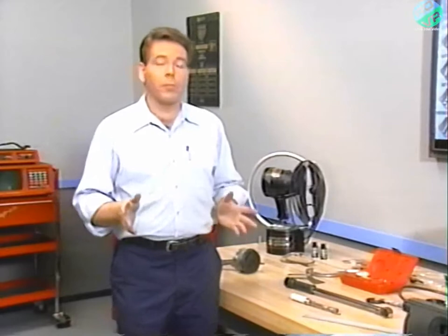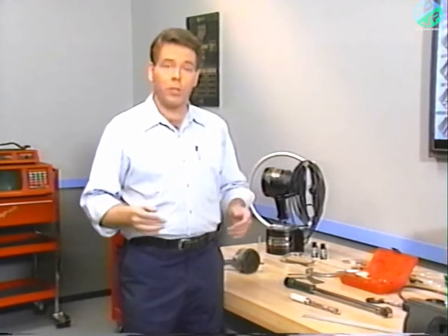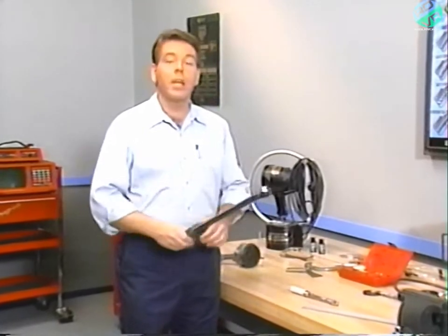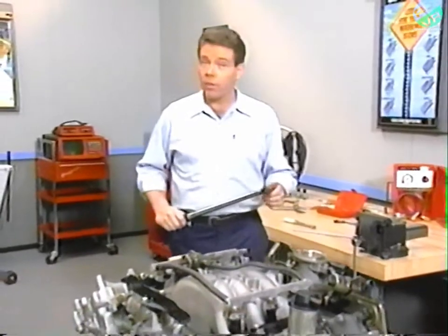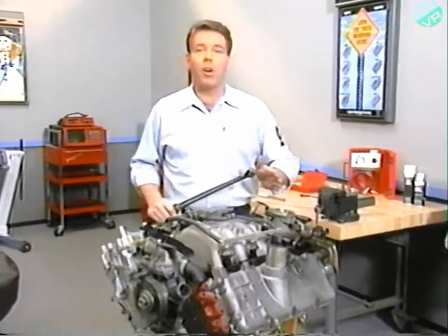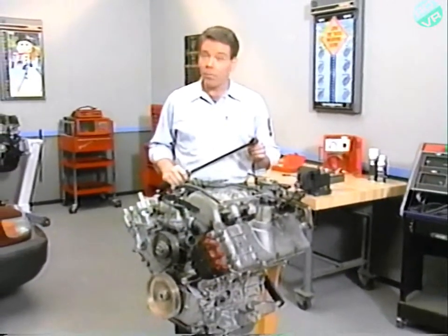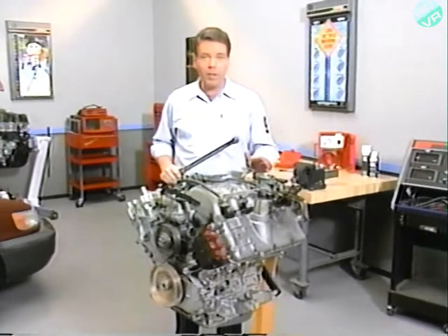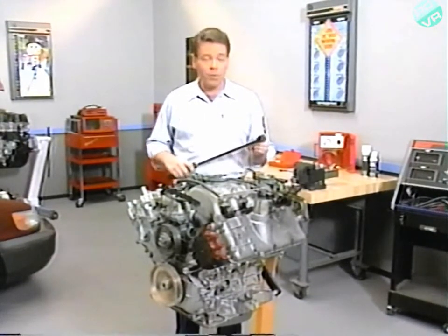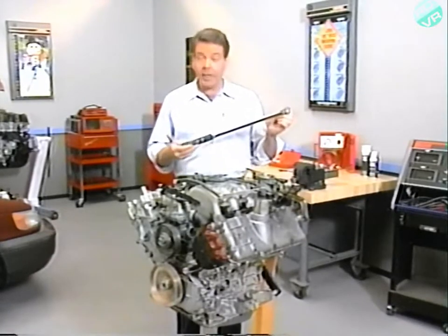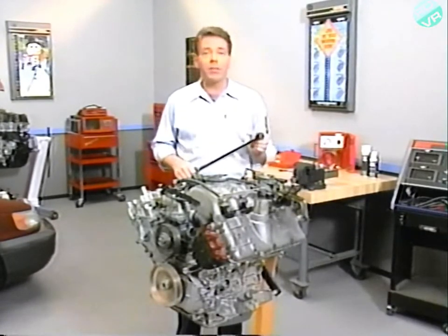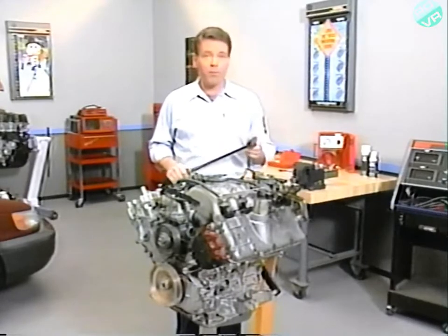Although bolt tightening procedures are often overlooked in the field, tightening fasteners to the correct torque in the correct sequence is just as vital to engine longevity as any of the other procedures covered in this program. Let's start by taking a look at the cylinder head bolt tightening sequence on the 3-liter PRV engine. Of course, you'll need a torque wrench for this. If you have access to a click-type torque wrench, it makes the process a little easier and quicker to perform.